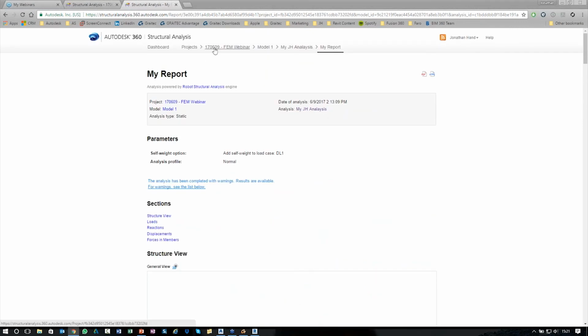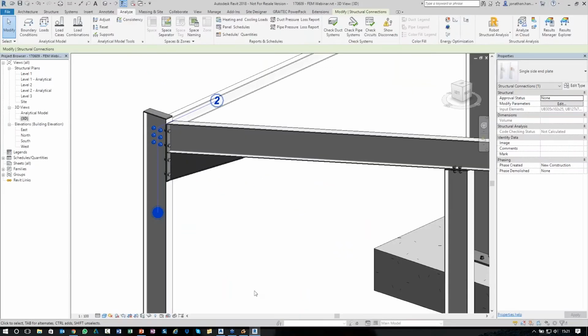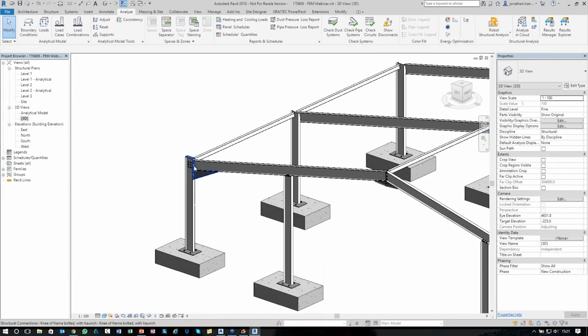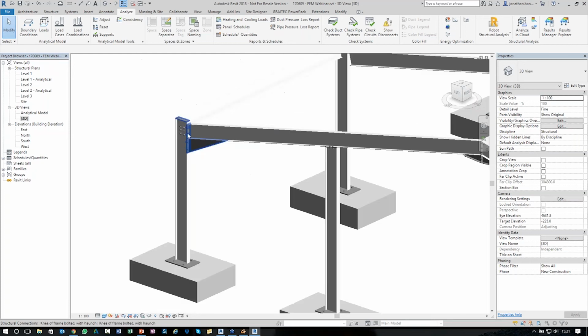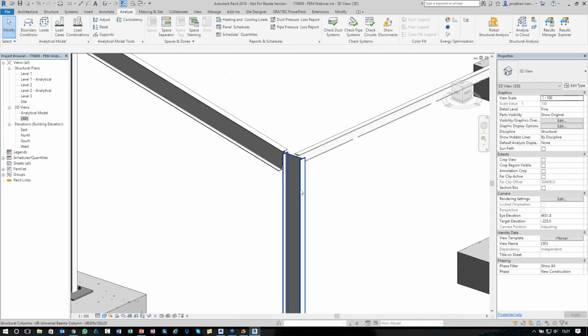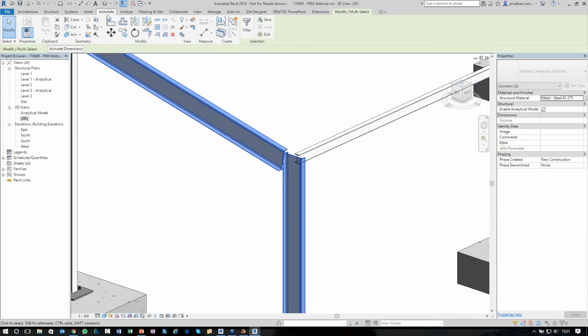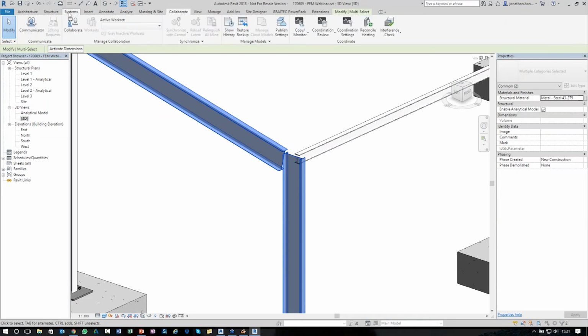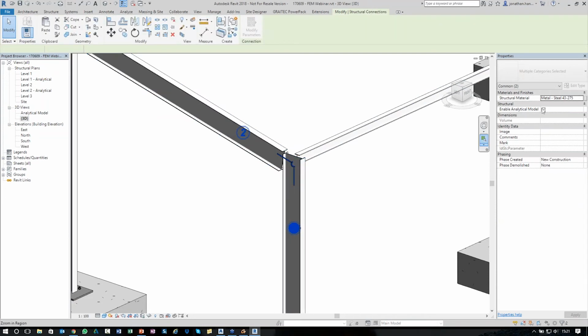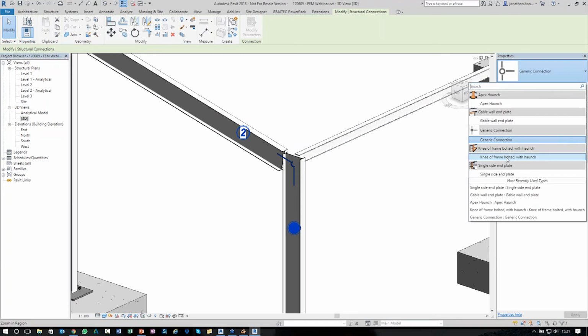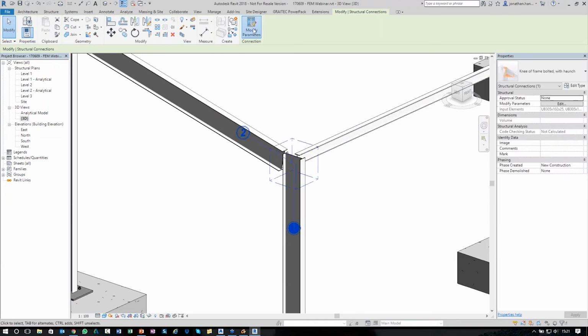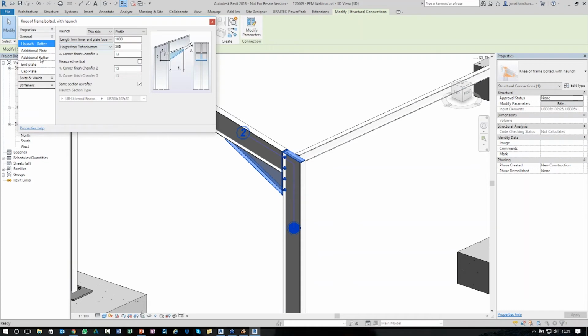Part of the workflow can also be, instead of going to the FEM model, we can send this to Advanced Steel. If we want to take this on to a fabricated model where we're producing part assembly and GA drawings, we can use the free Autodesk add-in. We've got the Advanced Steel extension. We can look at the settings. This can look at what we're exporting, what we're importing.